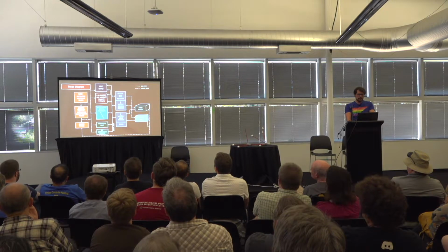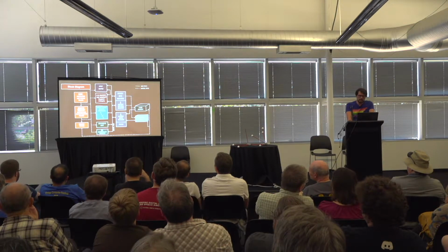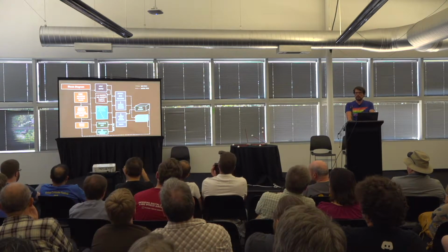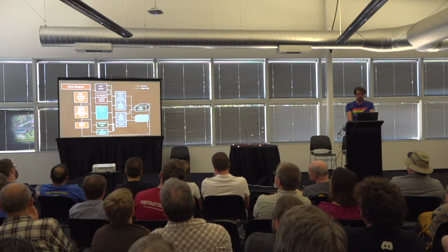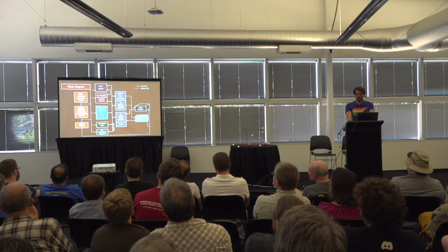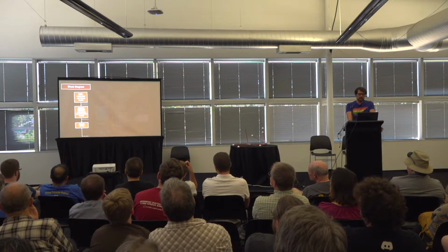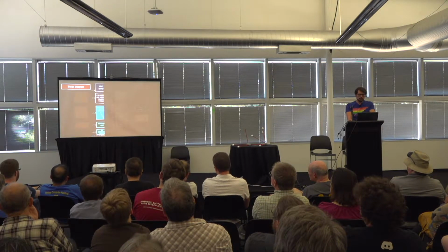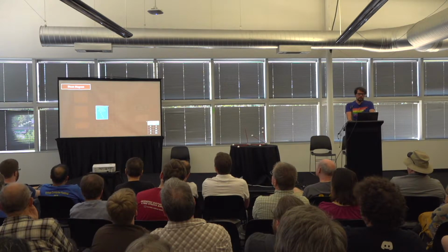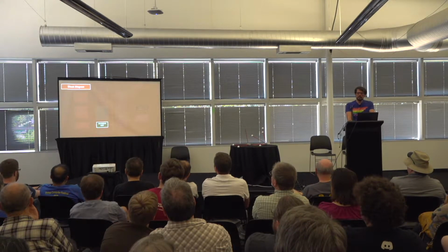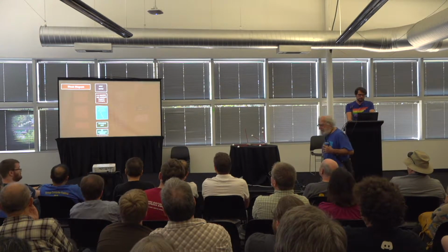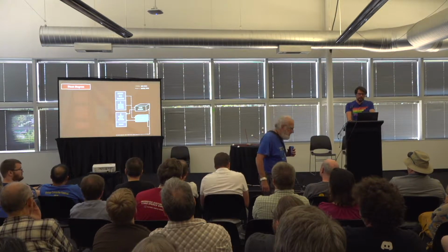This simplified block diagram shows the AGC at the hardware level. Each box contains on the order of 500 logic gates. The dotted lines are wires that move a single bit of information, and the solid lines are 15 wires that move a data word. These units deal with timing and control, and these are the central units. The central register unit stores A, B, LR, and PC, and the arithmetic unit can add and subtract numbers. And the memory components deal with RAM and ROM.